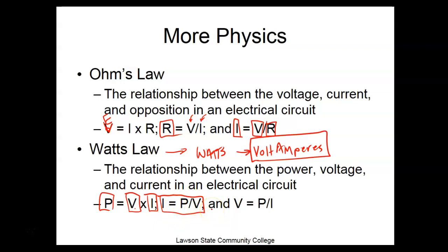And this is what Alabama Power is using, because if everything has a resistance, that means wire has a resistance. And V, how much voltage we drop in our wire, is equal to I times R. So the resistance of the wire is set by the material, it's set by the size, it's set by the length. And once you put that out there, of course, you can't change it.